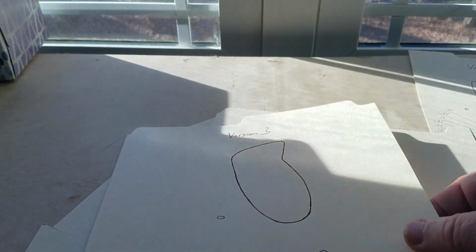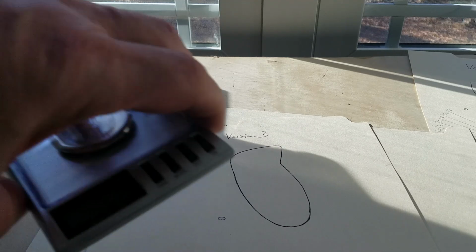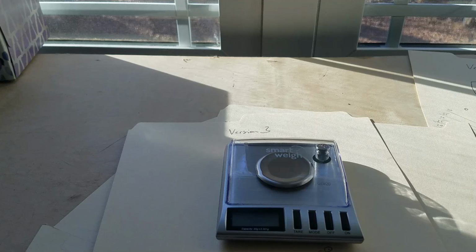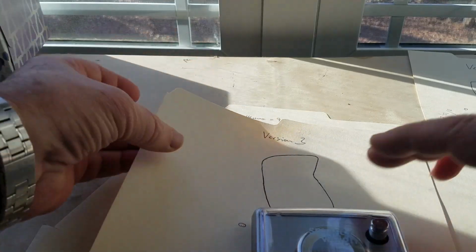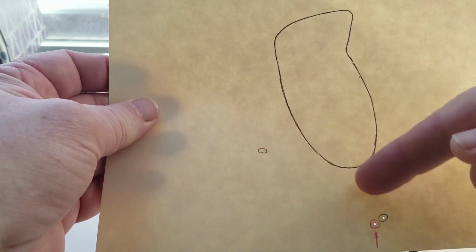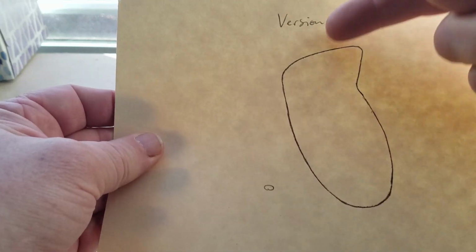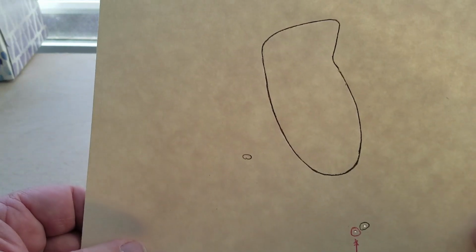So the way to figure out these weird shapes and their area, the trick is using a milligram scale. So this measures down to 1 milligram, and as I put those lines on here, I just cut off one after the other and measure the remaining area, which gives me the open air gap.